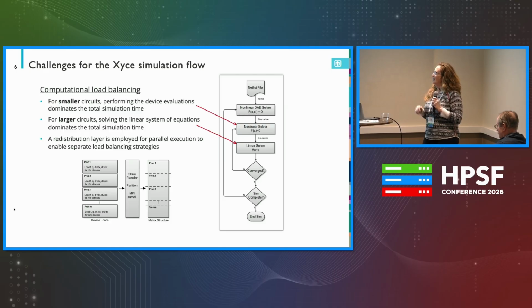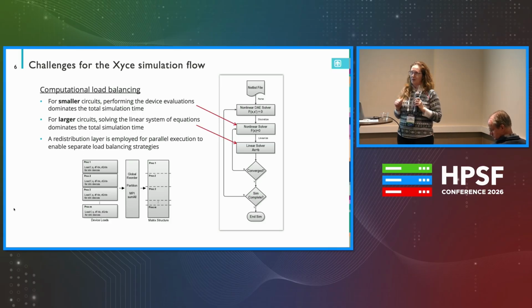It's amazing that, in particular for some transistor level devices, the equations that need to be evaluated are in the hundreds or thousands per one entry in a matrix. For a resistor, it's one equation. So your balancing is way off versus what your Jacobian, your matrix, ends up being. That's why we've put in these different load balancing schemes where we divide up the two, because we found in practice that it's necessary for Xyce to get the best scaling on both ends of this spectrum.